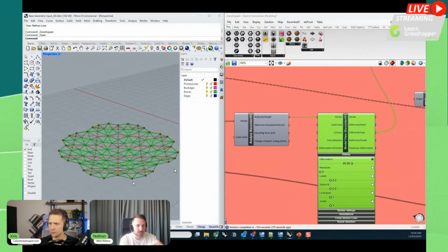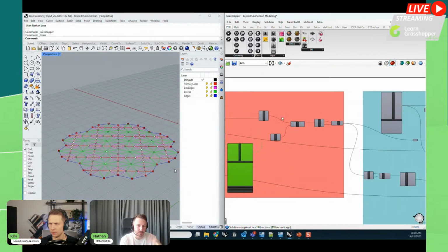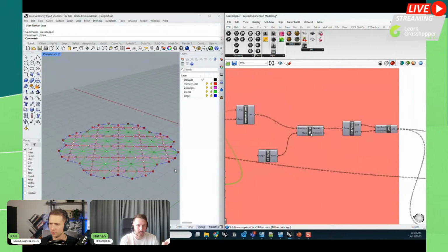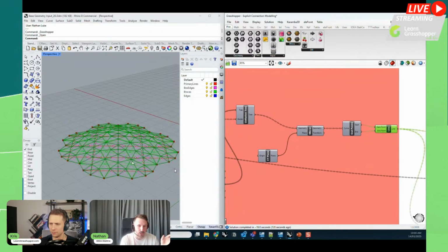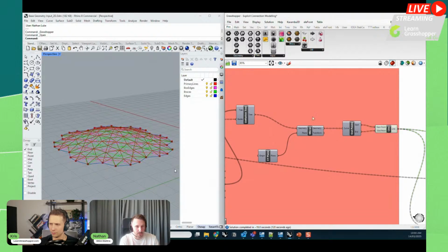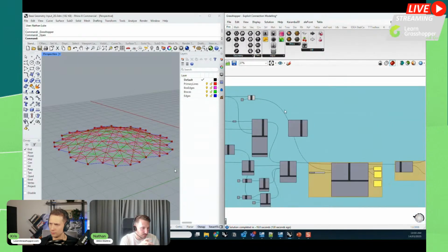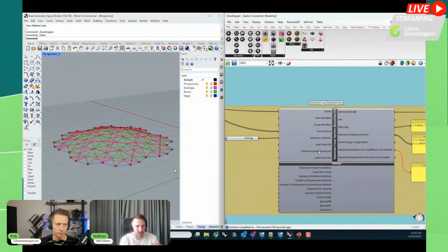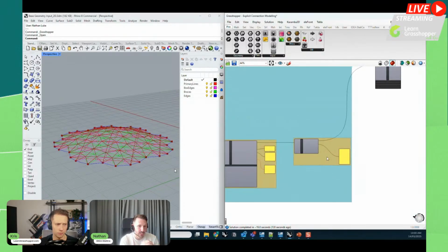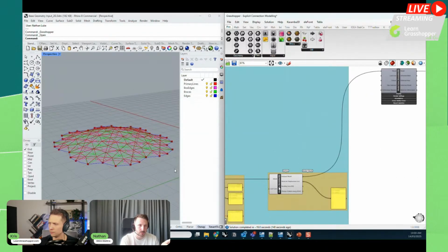We put a dead load on here, and we take that deformed shape and flip it to create that dome arch structure. So we flip that, we get our arch structure, we keep the grouping, and then we create another Karamba model which does the analysis on our form found model.